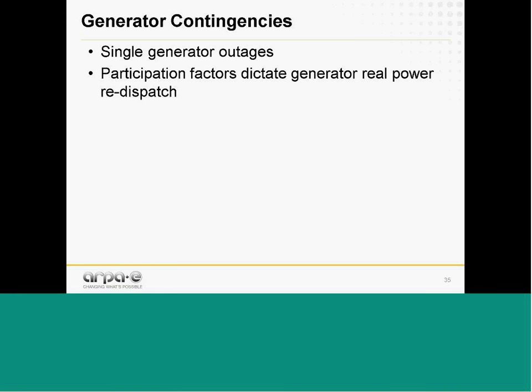In this security-constrained optimal power flow model, there's a very much similar situation here. This is going to be a bit more complex, though, because California ISO is not making sure that if I'm already operating at Pmax and you're expecting 100 megawatts from me, their model as of right now proposed will violate that. And they're okay with that, but we're not going to allow that. That's where the complementarity issues come into play.